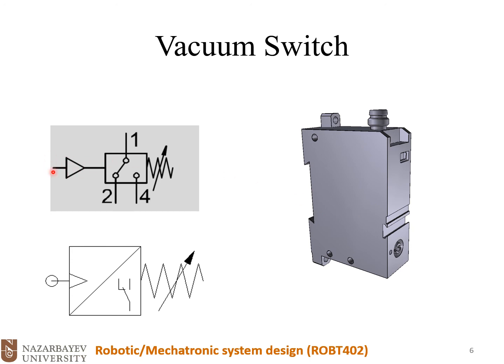And if the vacuum pressure drops, then the vacuum switch will again turn on that directional 2x2 valve. Because of course the circuit that I presented is the ideal one, but in a real system we could have some leakages of air from the atmosphere